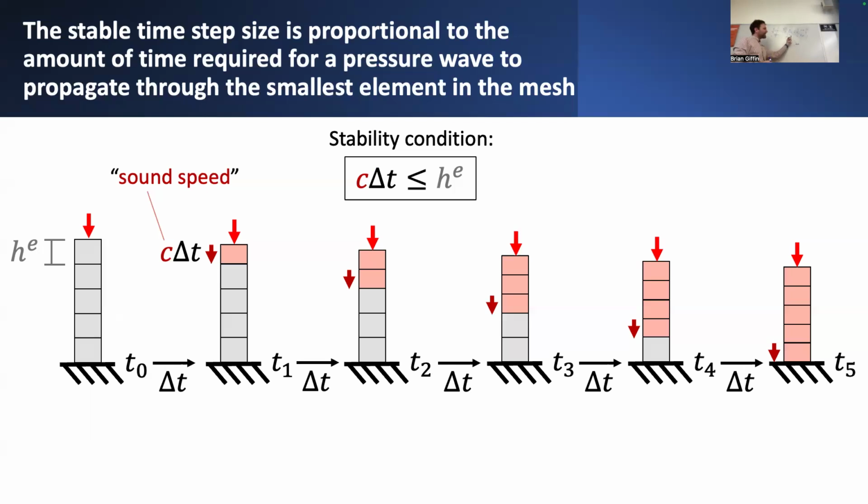So it's possible to set this delta t value such that the resulting eigenvalues of this update matrix are always less than 1. And that's precisely the condition that says, if I'm updating the state of the solution, it's at least not going to become unbounded. If anything, it'll actually start to diminish the magnitude of the solution. So there's some kind of numerical dissipation, is sometimes what it's called. But effectively, that's how you derive a lot of these conditions, at least in the mathematical sense.